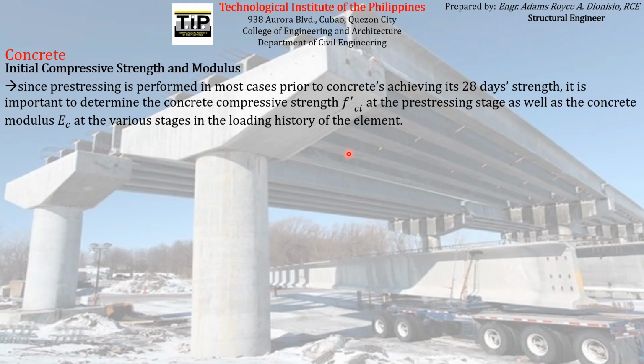After the concrete pouring, after some time when the concrete has already achieved enough strength to withstand the pre-stressing force, or the compressive force that will be applied by the pre-stressing reinforcement to the concrete itself, when the pre-stressing reinforcement is cut, you can see that the compressive strength of that particular concrete is not actually equal to its 28 days strength.